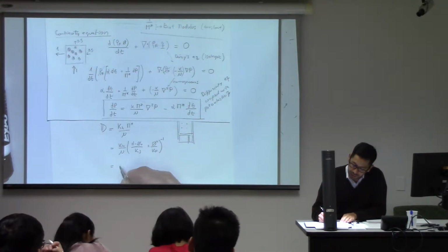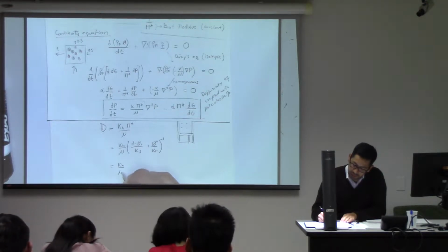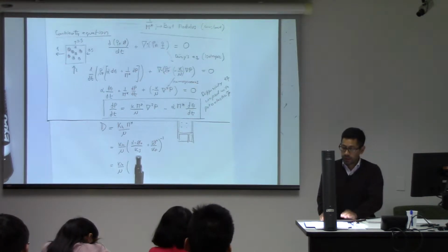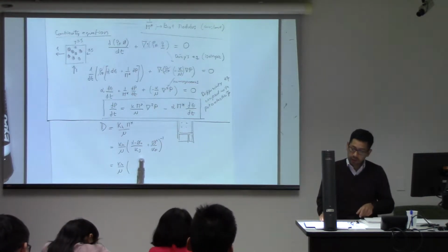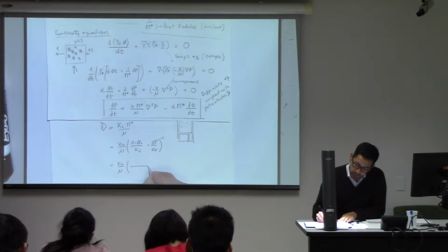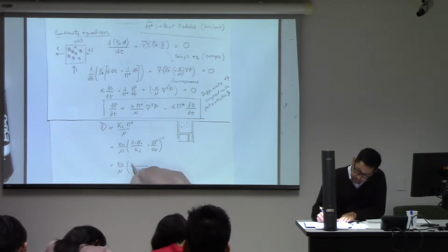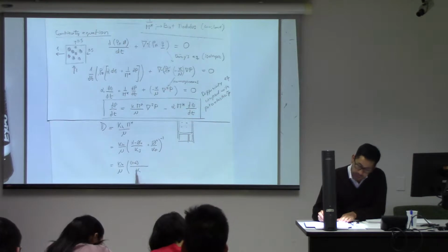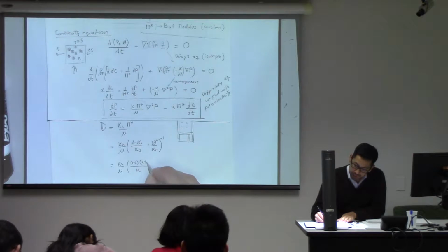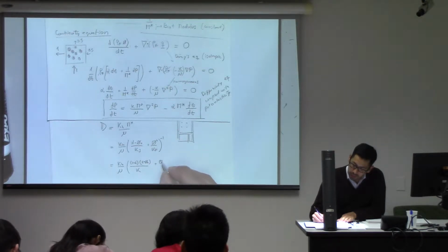You can further modify this equation. Sometimes we do not measure Ks. Ks is not a direct quantity; it's more like an indirect quantity that characterizes the porous medium. So instead of Ks, we can work with K, and if I replace Ks from the definition of Ks, this is going to be 1 minus alpha, alpha minus porosity plus porosity Kf minus 1.